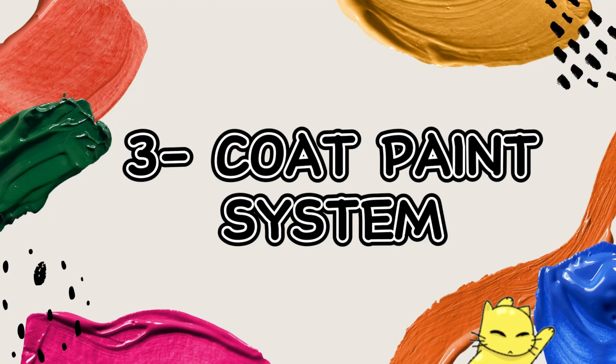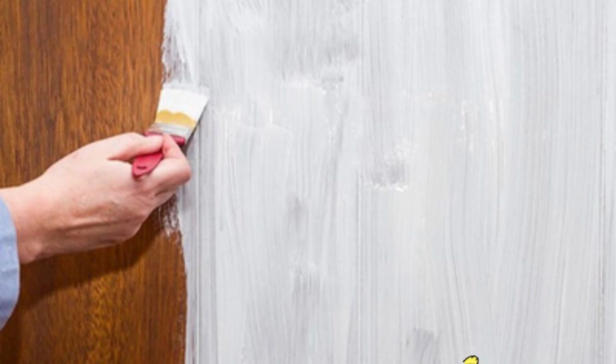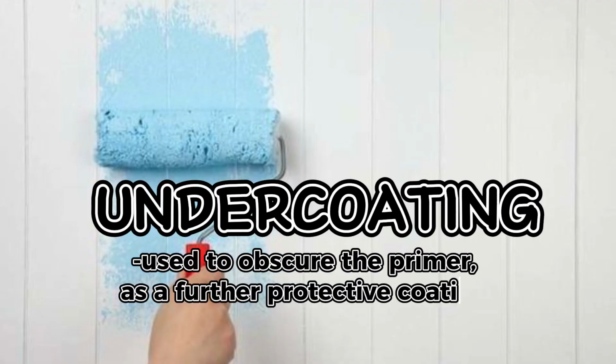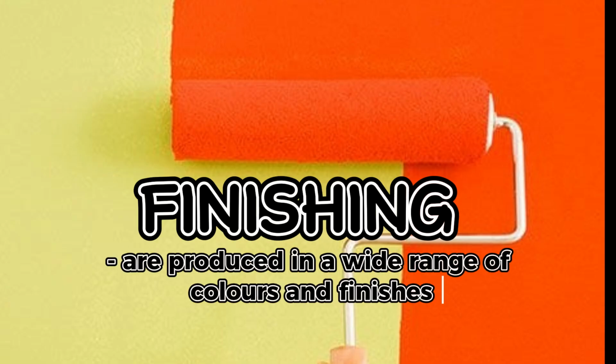In order to achieve a smooth and even surface, we have a three-coat paint system, which is primer for the first coat to seal and protect the surface. Undercoating paints, sometimes used to obscure the primer as a further protective coating, and lastly, finishing paints that are produced in a wide range of colors and finishes.